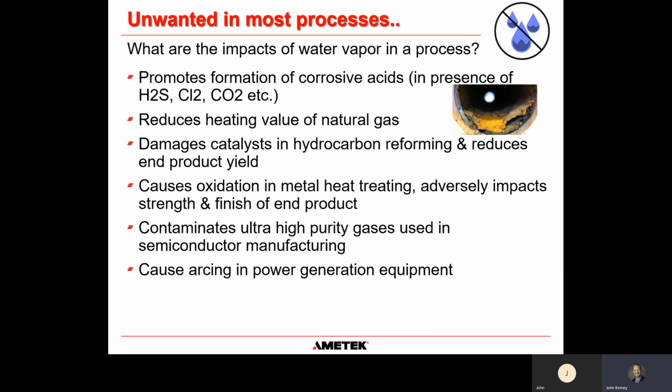Within natural gas, water vapor impacts the heating value or the BTU content of natural gas. How well does it heat? In the downstream space, such as in refining or the petrochemical space, catalysts are typically used as part of the reaction vessels to produce different types of end products. And the catalysts are typically made up of very high-priced metals, platinum as an example. And water, if it's in the feedstocks going into the reactor, can damage the catalyst itself, which is an expensive problem. But water can also reduce the reaction yield and end up producing less of the desired end product. So it affects reaction yields and so on.